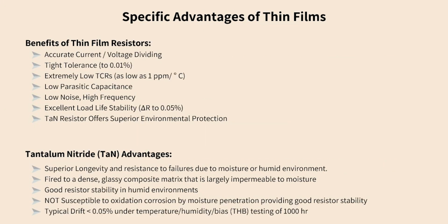Thin film resistors stand out for their precision and stability, which makes them a preferred choice for demanding applications. Their ability to maintain tight tolerances as low as 0.01% and achieve exceptionally low temperature coefficients of resistance, or TCR, ensures accurate performance even under changing environmental conditions. Thin films also offer minimal parasitic capacitance and low noise, making them ideal for high-frequency circuits and precision measurement systems. These benefits result in reliable, consistent performance over extended periods, particularly in sensitive electronic applications such as instrumentation and communication systems.